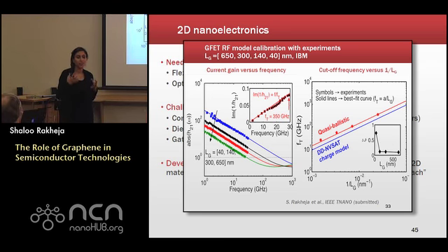So you said here you actually have different channel lengths. Yeah. But still, if the contact resistance is not scaling at all with channel length, and you make your channels shorter and shorter, the overall device tends to get limited by what the contacts are really doing. So contacts are not becoming any better with technology, with gate length scaling in this particular case. And then again, the question is, if graphene does not have a band gap, then why does it even saturate for longer channel devices? Have you simulated the ID-VG?